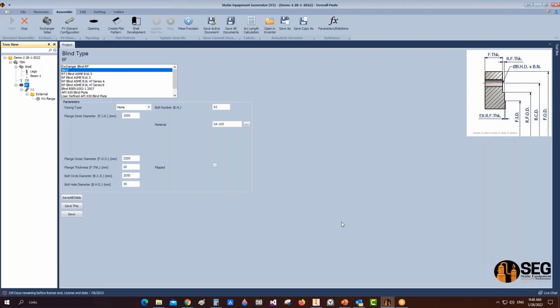Would you mind to say your question again, because I cannot hear you? Yeah, for the nozzles, okay, example 24-inch manway nozzle. Normally we use standard 24-inch flange and the blind flange, right? Instead of standard flanges, we use customized plates. For the flange, instead of 16.5, we use a 16 mm plate which is welded to the manway neck. And that blind flange also, we take it as a 20 mm standard normal plate instead of standard in some cases where atmospheric pressure is there.